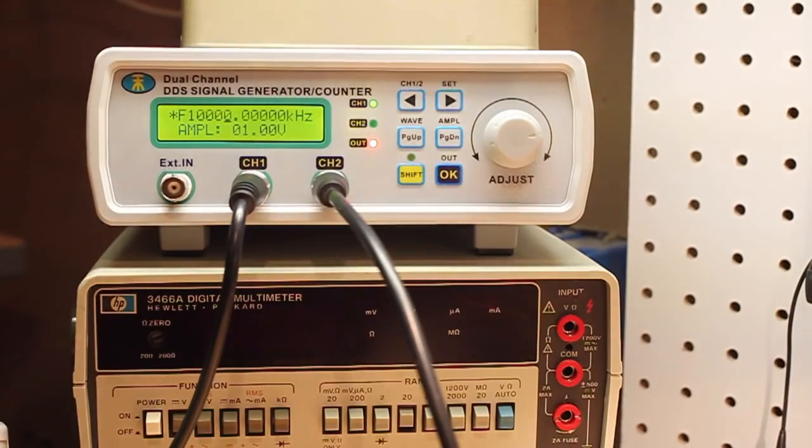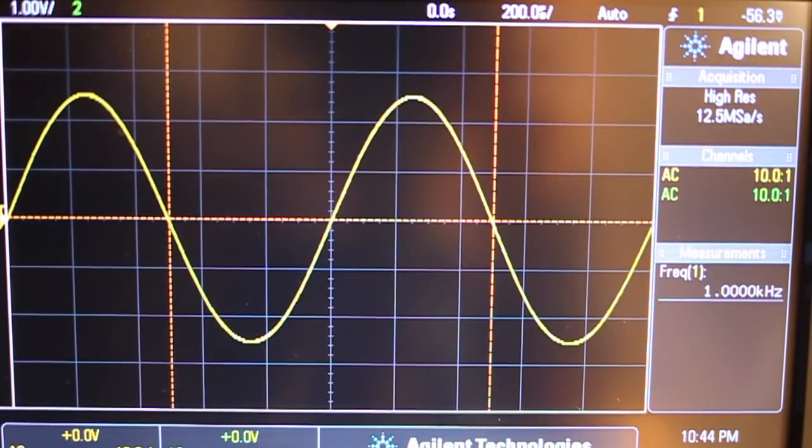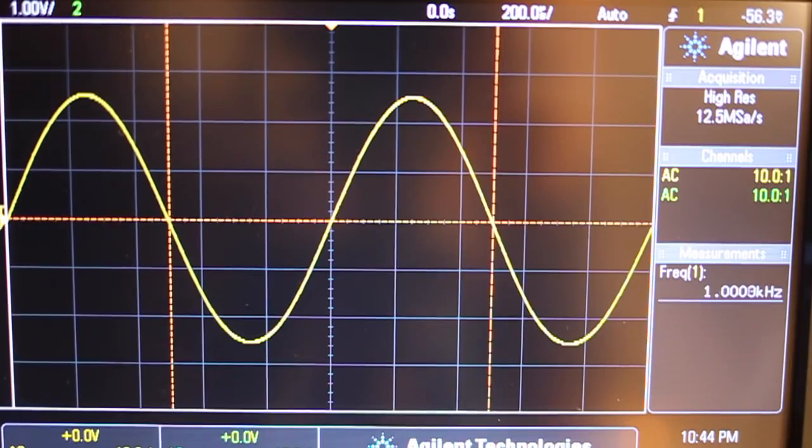So there's really no way to easily distinguish between a frequency that is 1 kilohertz above or 1 kilohertz below my local oscillator. And the reason that we can't tell the difference between a frequency that's above or below our local oscillator is that in this configuration with a single mixer, we're not getting all the information about the signal that we need in order to make that determination.